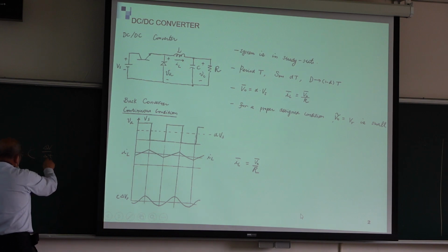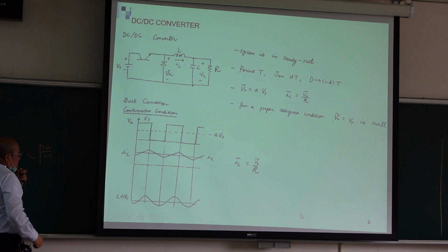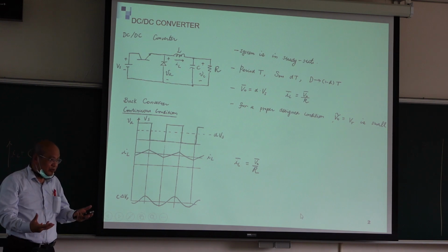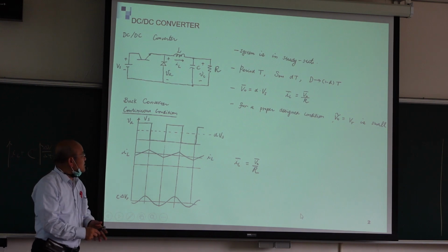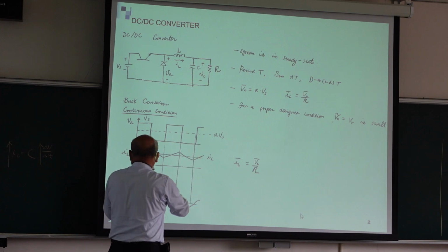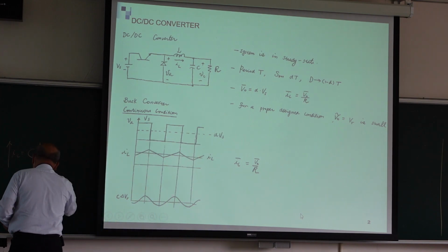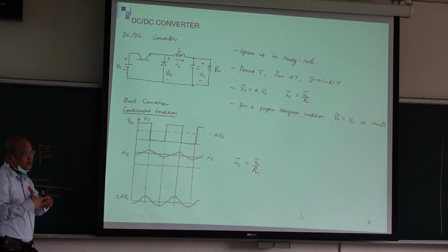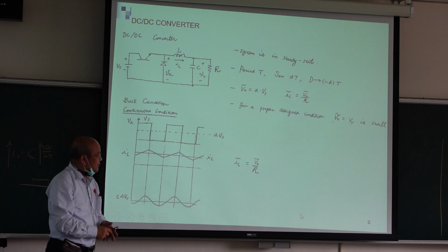Then when you change the voltage, this is very huge, and your capacitor current becomes very huge. Then you damage your capacitor. So you need an inductor here. Can you remove the capacitor? If you remove the capacitor, then your output is like this. But you need a very smooth output. So you need a capacitor, right?